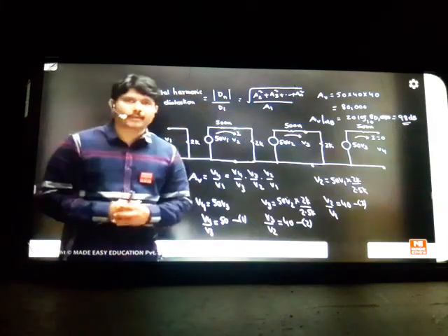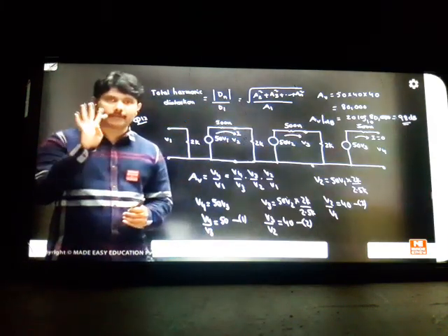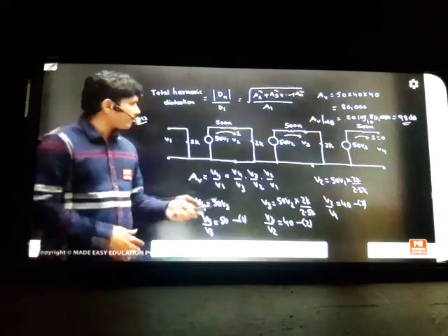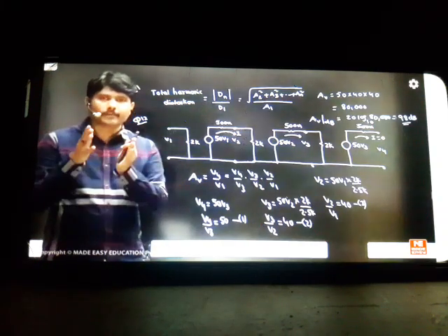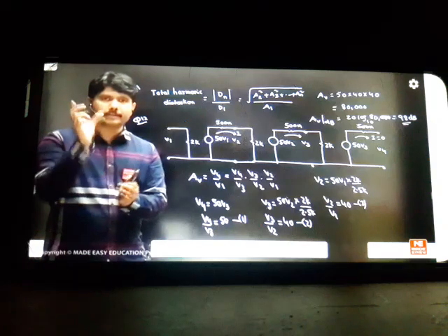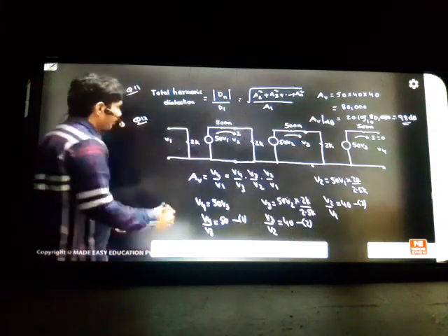Shavnikas, can you see your first topic? What I taught in our class? Basic types of amplifiers. 4 topics I taught for you. Again you're asking me, sir, how to write the diagram. A diagram: take the feeling as voltage controlled voltage source. Input you have to represent Zi. Output you have to represent a voltage source. Any practical voltage source will have a series resistance called Z0. This is your first topic, which I taught in your notes.